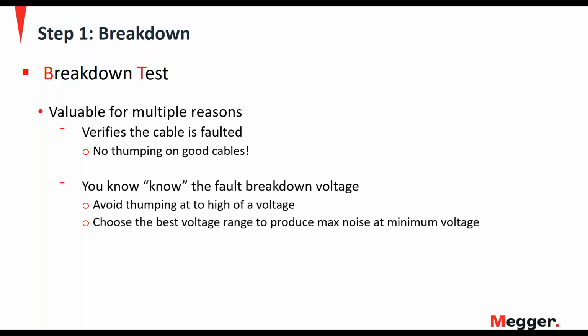Probably more important, on that faulted cable, we now know the flashover or breakdown voltage of that specific fault. So we can avoid thumping at too high of a voltage, and we can choose the best voltage range to produce maximum noise at minimum voltage.